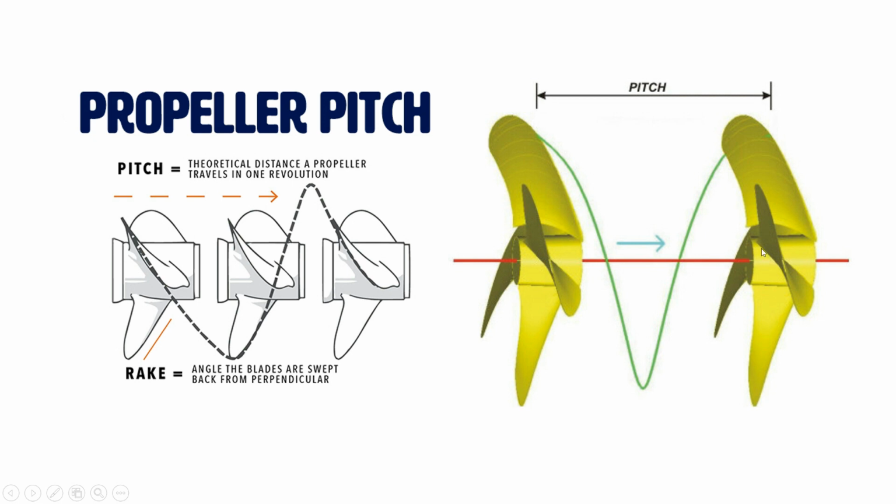If it is not attached to any aircraft, say you have a screw thread with an external thread and the propeller contains an internal thread, then if you move the propeller on that screw thread, the horizontal distance covered by the propeller is your pitch.